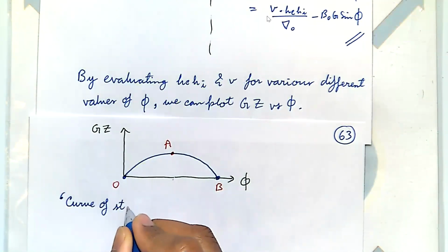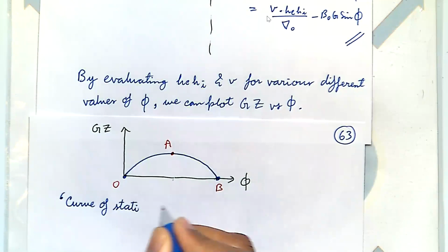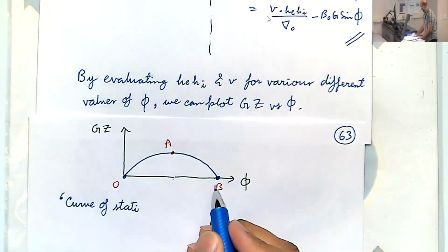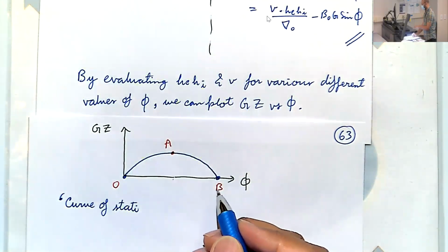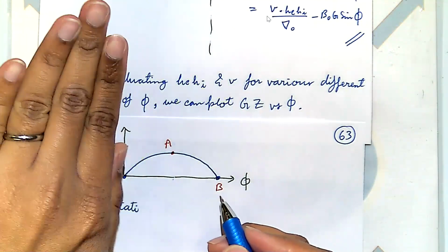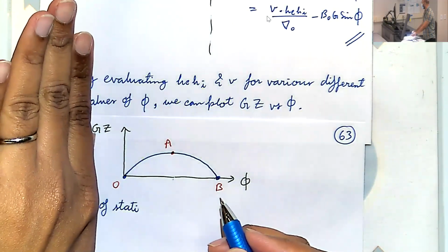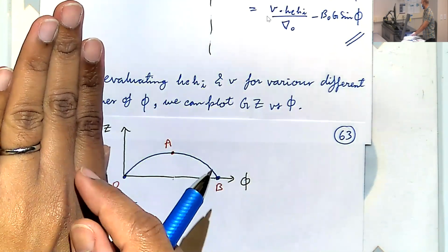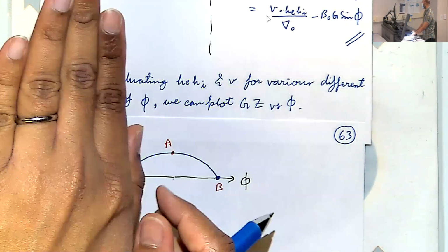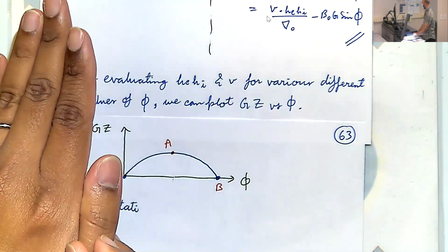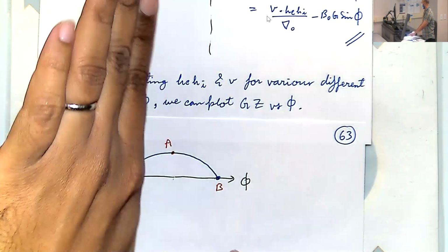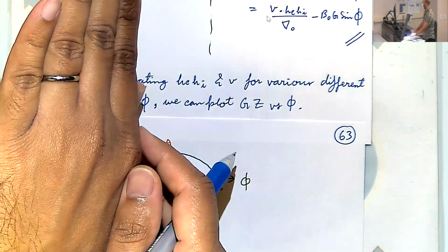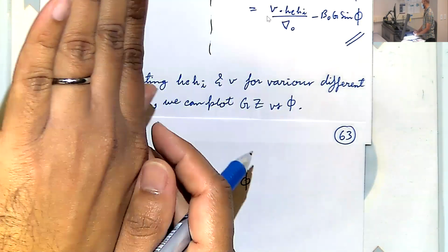At what point did you say it capsizes, at A? At point A or? No, at B. Think about it. If you're heeled and there's a little bit of restoring torque, fine, it'll still try to upright you slowly. Okay. When you're at A, the restoring moment is the maximum, so it tries to really upright you very, very quickly.